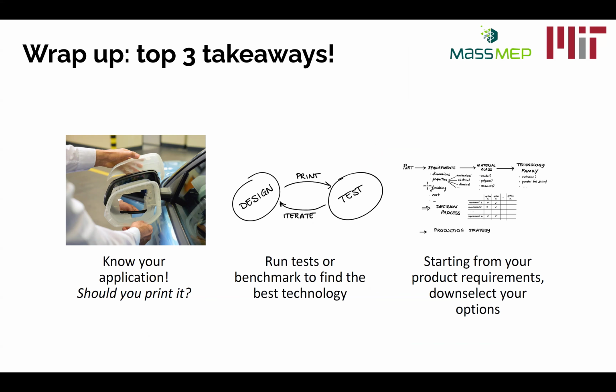So think through the ways that your design, not just your geometry, but also your process settings and material and so on, can fail quickly, fail cheaply, develop learnings, and cultivate those back into the next print run. Try to be efficient with your time, as well as learn ways to experiment inexpensively, both in terms of dollars, but also in terms of resources.